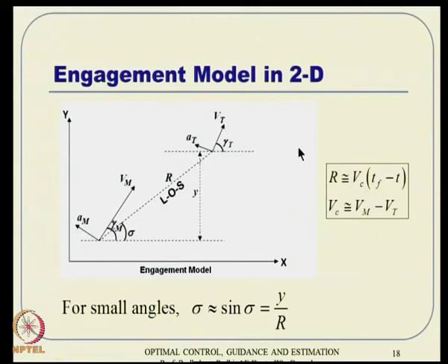So that is some typical geometry and the concepts used in missile guidance. Now the whole idea here is that I can nullify this difference in y. That has to go to 0. This direction should also go to 0; only then can it intercept. So the y direction error will be killed through the guidance formulation, whereas the x direction error will be killed through an appropriate estimation of time to go.